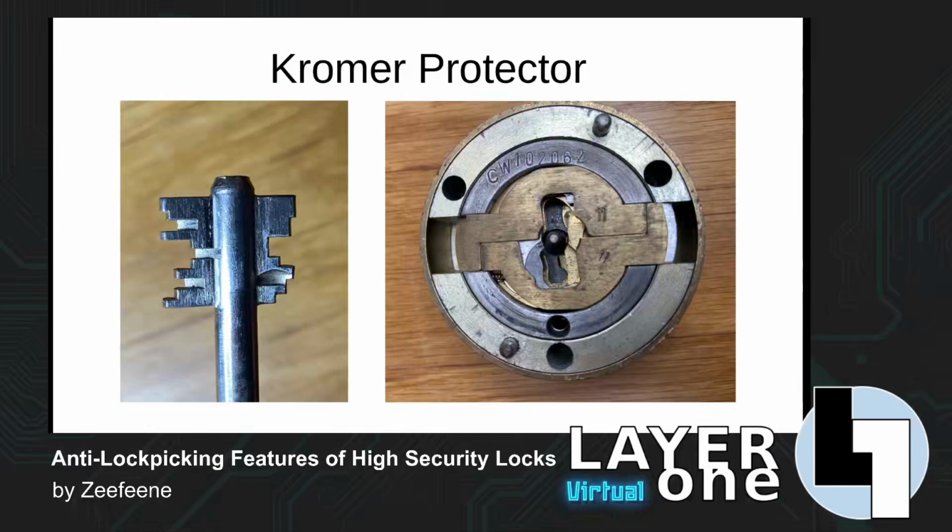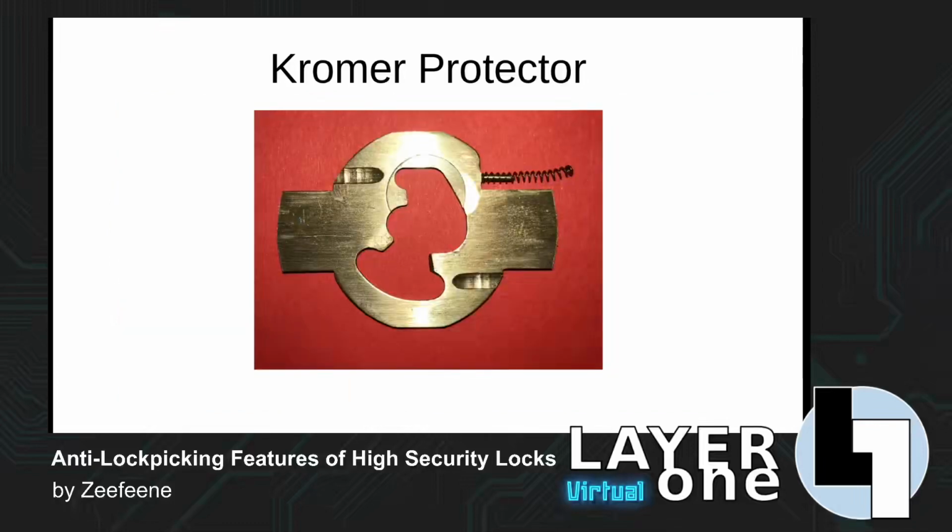But I guess the reason is because most people don't believe that one of the most secure locks ever designed is actually a wafer lock. The thing that is particularly secure about this wafer lock compared to conventional wafer locks that you will see on low security cabinets and that sort of thing is that the wafers look like this, and the key only can apply tension to the core via the wafers.